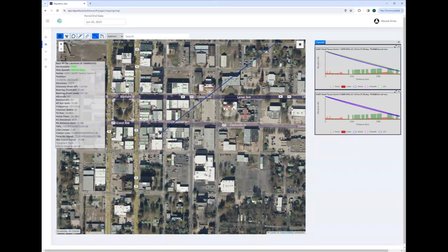We always just kind of put a standard 2 dB line loss in there. We have a clutter loss, which is any clutter it happens to be going through. And you can see over here, we've got some trees at the end of the path. So our clutter loss was 14 or almost 15 dB here, based on the distance we traveled through that. And then our total received signal is -75.